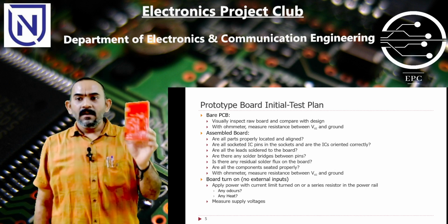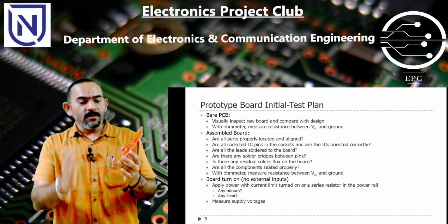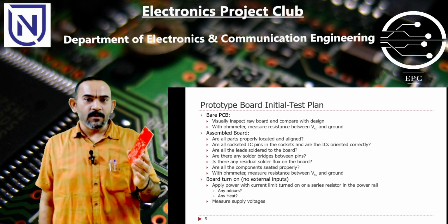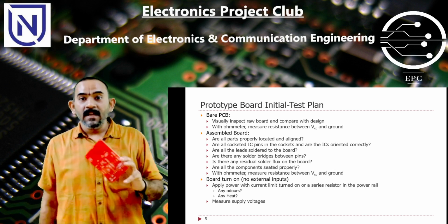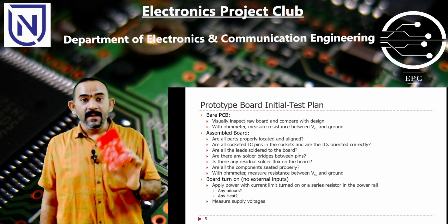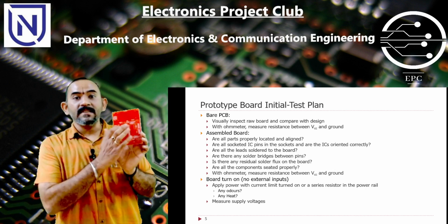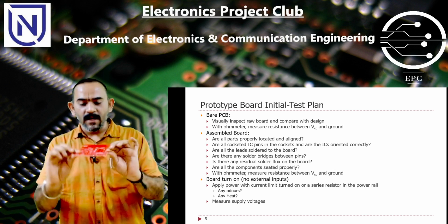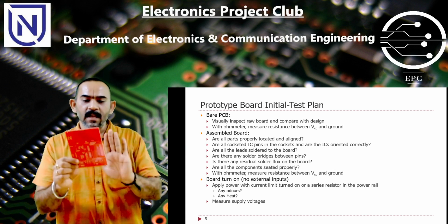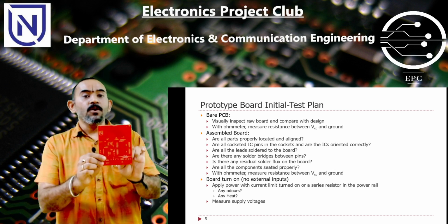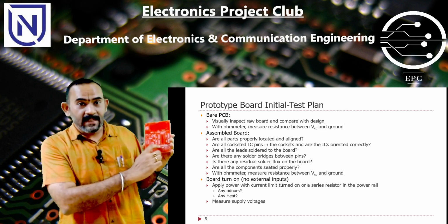Now after this, you are going to mount the components on this to complete the assembly of the board. There are some steps you have to take in order to ensure that the board works as intended. The first thing is you are going to test this bare PCB. There are some minimum tests you need to run on a bare PCB. You have designed this, you know it is supposed to work in a particular fashion, you know how each and every pin is connected.